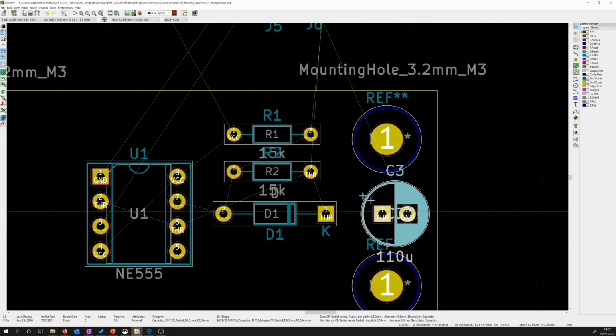And from the capacitor to ground, since we have a ground plane on the backside, no problem to layout. But we have here the threshold signal crossing these lines from D1 to pin 7 of our IC. But it's not a problem, since we can route the threshold signal between these two pins to the threshold pin of our IC. So that's no problem for routing. This looks fine for me so far.